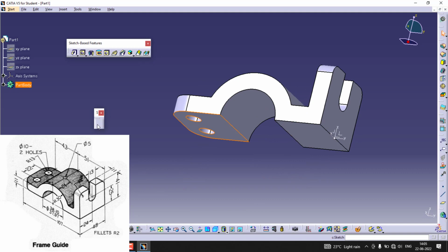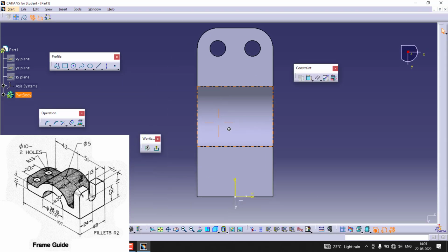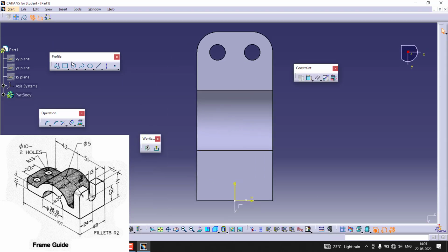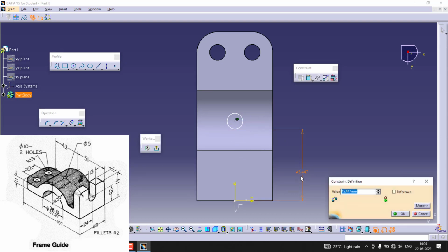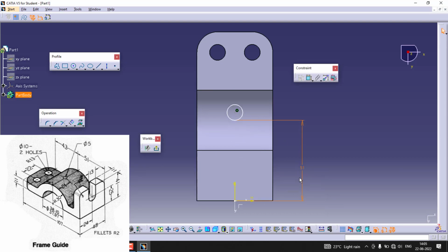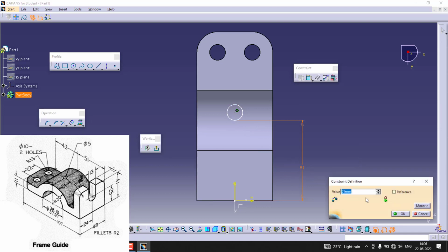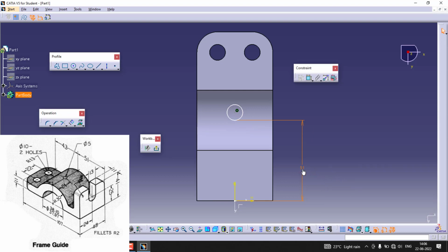Next thing is to sketch one more, simply this oil hole. Can refer the origin, and here the distance, it is 51. Oh, this is not from the center, it is 51, not from the arc. Delete this. You don't have the option to change.